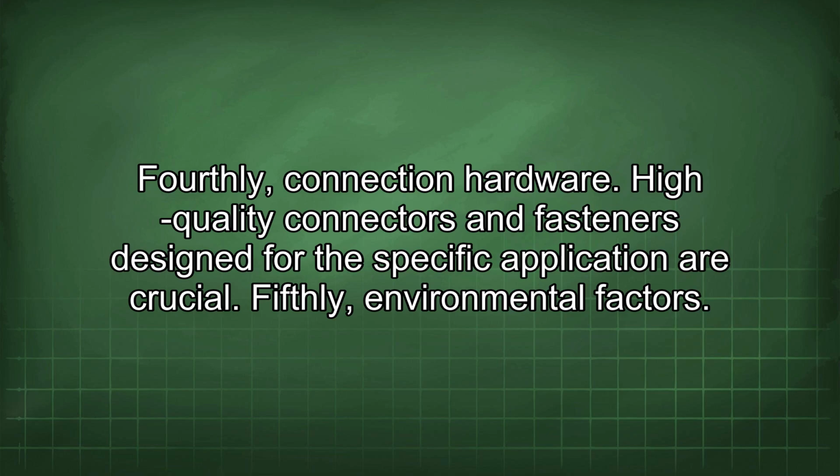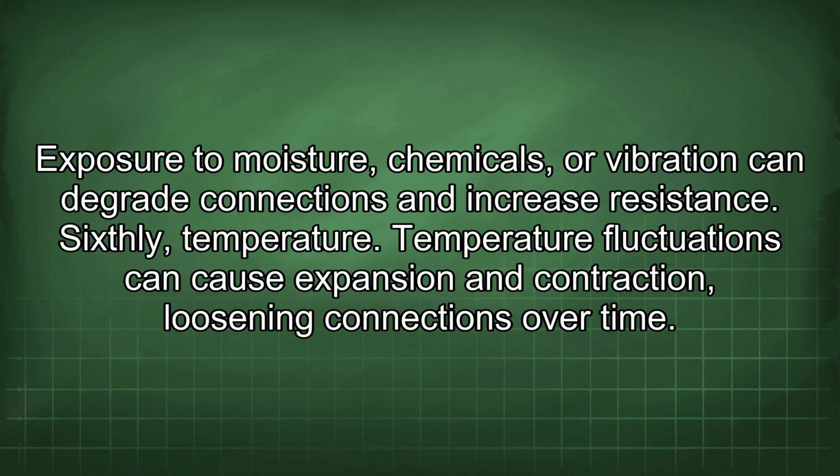Fourthly, connection hardware. High-quality connectors and fasteners designed for the specific application are crucial. Fifthly, environmental factors. Exposure to moisture, chemicals, or vibration can degrade connections and increase resistance. Sixthly, temperature. Temperature fluctuations can cause expansion and contraction, loosening connections over time.